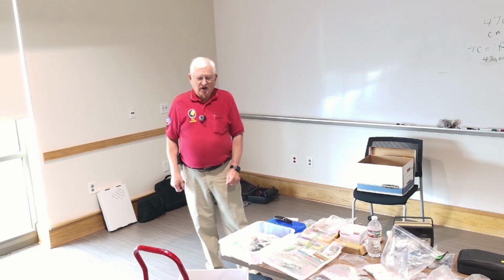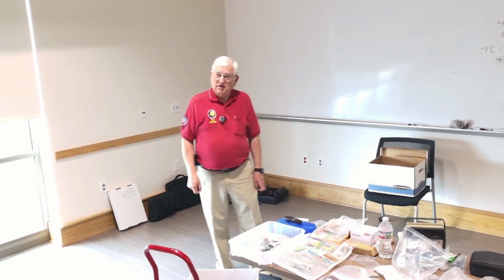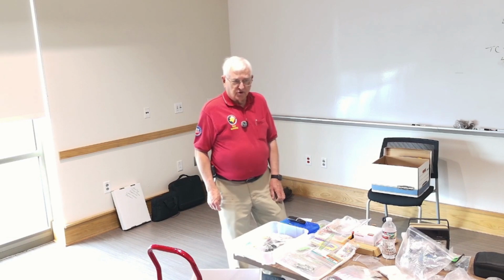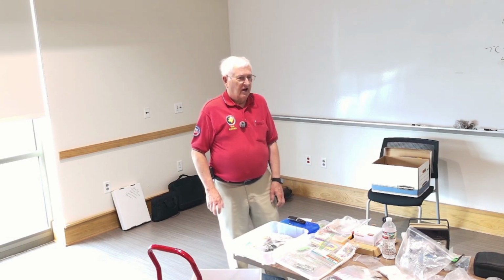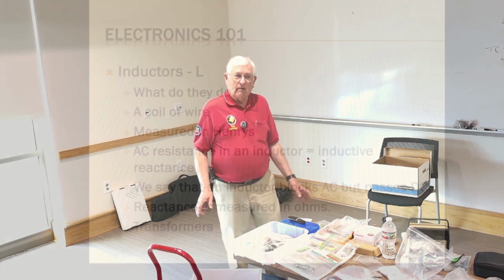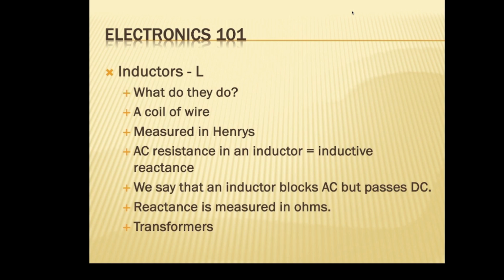One of the little gotchas to watch out for is resistors. Resistors can be made up of a lot of different materials. Most common one is carbon. The resistance in a carbon resistor is controlled by how densely the carbon is packed. The more densely, the less resistance. That's the idea behind it. Those resistances were pure resistance. There's no inductance, there's no magnetic reaction in that whatsoever.